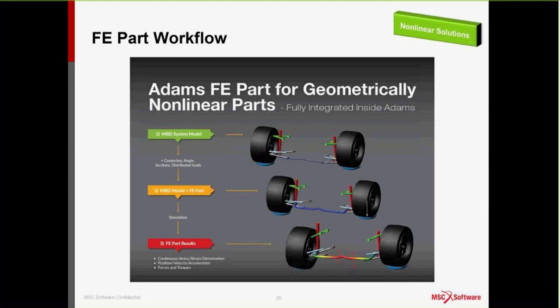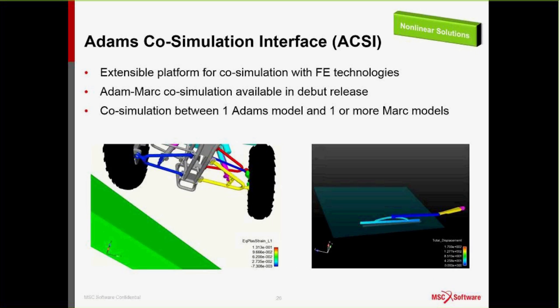So the workflow is pretty straightforward, and I won't spend too much time on it, but you can define the center line of your beam element and then construct using this little utility in the UI. You can construct your ANCF beam, and then you have nice continuous stress and strain as opposed to what you might see with a piecewise continuous, discrete flexible link type approach.